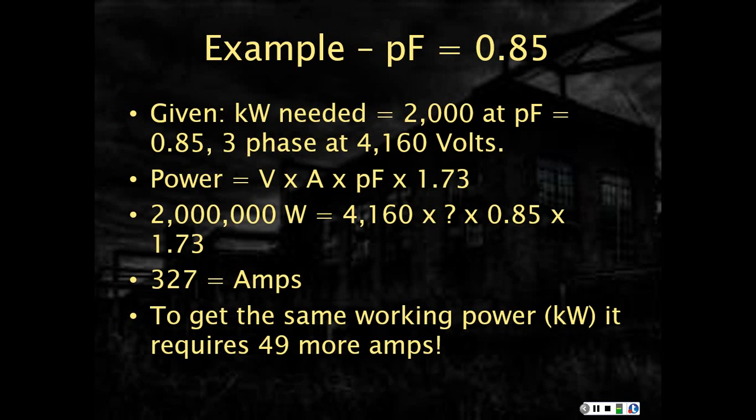And this time when I solve for amp draw with the new power factor, my amp draw has gone to 327. I'm still needing the same working power. That hasn't changed. But it requires 49 more amps to accomplish that mission.